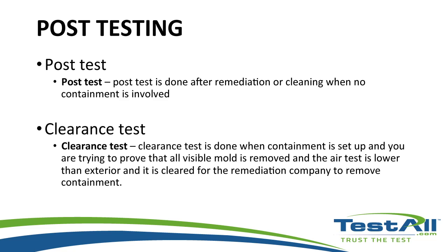Post-testing could be done in 2 ways. One would be straight post-testing, where after a remediation is done, you'll go in and do post-sampling. The other one is if they have to set up containment. During that case, they'll want a clearance. They'll want you to go in and make sure that you take your samples, you view the area, everything has been removed and clean, and your samples show that indeed the mold problem is resolved, clear to take your containment down, good to go.